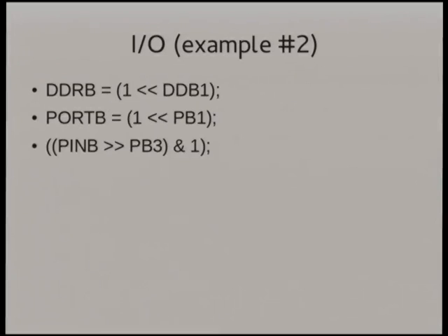So that means you can actually rewrite it a lot neater, and now you can actually see that the values make sense. Because it's all binary, you can just do a binary OR to mush the numbers together, and pack them into the same byte, so you can do more than one thing at a time, which is something that you can't easily do using the Arduino libraries. You have to do, I'm going to do a digitalWrite and a digitalWrite and a digitalWrite to set 3 pins. With this, you can do all of those pins in a single port in one instruction.